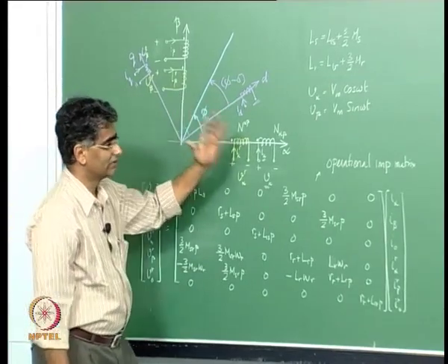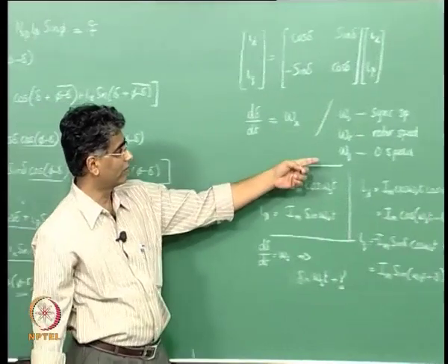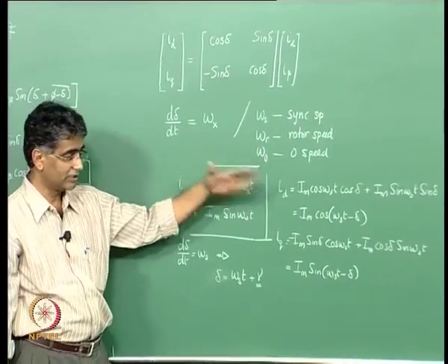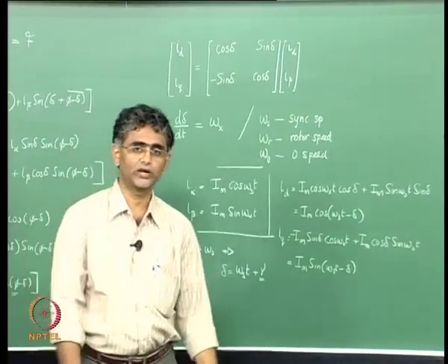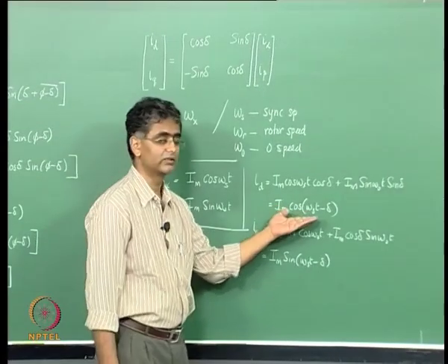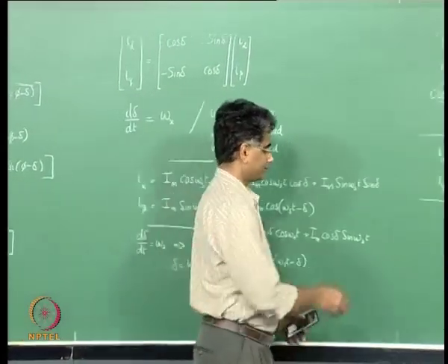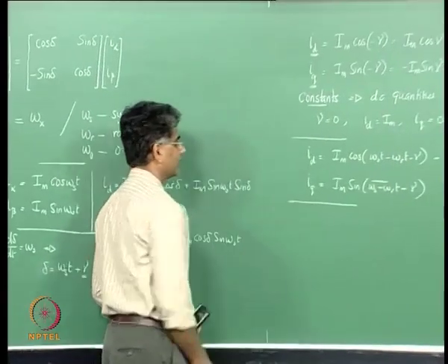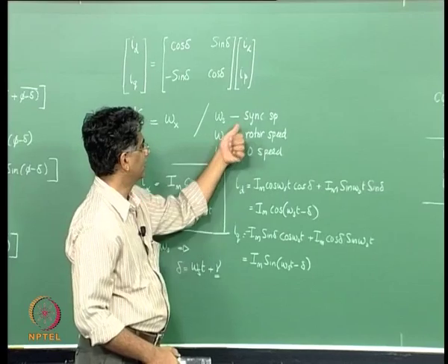So if the reference frame is not going to rotate and the speed is 0, it amounts to simply shifting the axis by some angle, and therefore since it is stationary the excitations are all at supply frequency. So with this one can choose whatever reference frame you want.